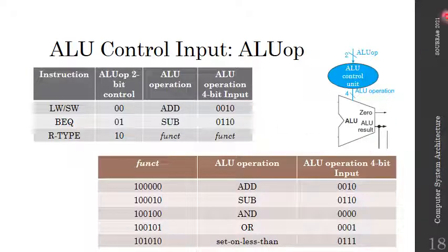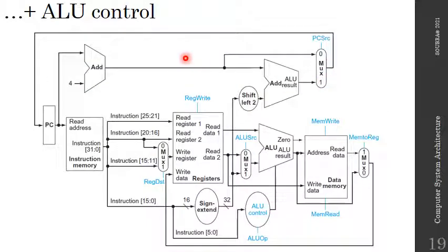Alright, so typical final exam question. I'm giving you that schematic here, and I'm telling you that there's still something missing in order to cover everything here. What is it? So for sure I'm reading the ALU operation that I'm expecting, so this is done by here. For sure I'm generating this, but there's still something missing that I haven't covered. What is it? Well, you can notice here that I still don't have the funct. So I need to feed the funct to the control unit as well. We good?